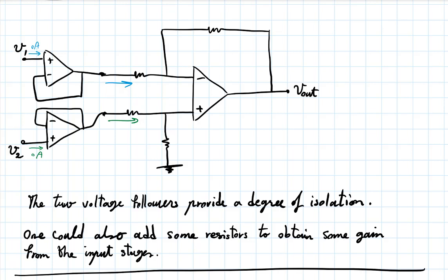And so this concept of stacking op-amp circuits like that, having something with some gain and then multiply. You can even stack 3 stages of gain. Imagine you want a gain of 1 billion. If you wanted to do it with a simple inverting amplifier, your ratio of RF over R has to be 1 billion, right? So you need a 1 ohm resistor and a giga-ohm resistor. Something about it doesn't sound right.